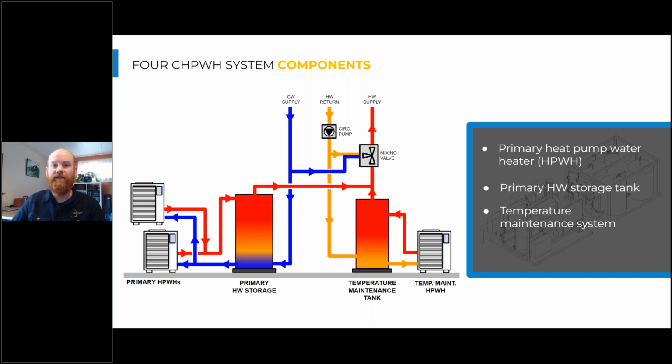So we're typically targeting 10 to 20 seconds of response time. So as soon as someone opens that hot water tap, there's going to be hot water coming out of that fixture, hopefully within 10 seconds after opening that tap or turning on your shower. And so to do that, we typically have a hot water circulation pump or some other means to maintain temperature in that hot water distribution network of piping.